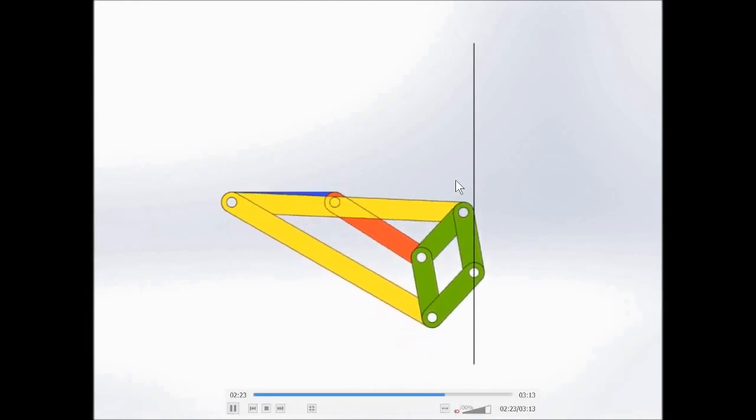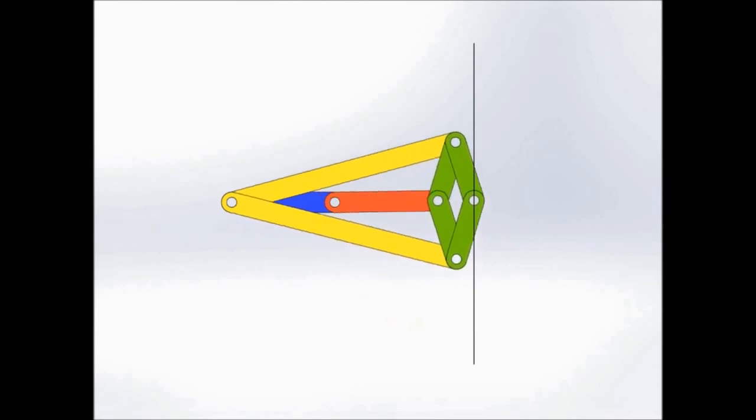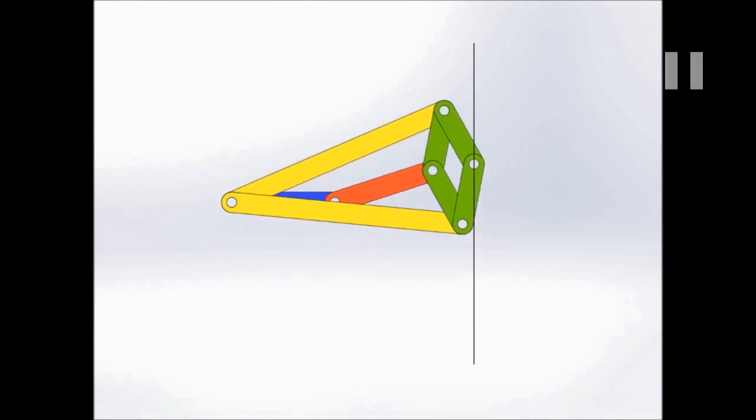It will be an exactly straight line. Yes, an advanced mechanism, and here you can see a number of links. The condition for this is that these four links should form a rhombus. These four links will be equal, otherwise the opposite links will be equal. That is the first condition.